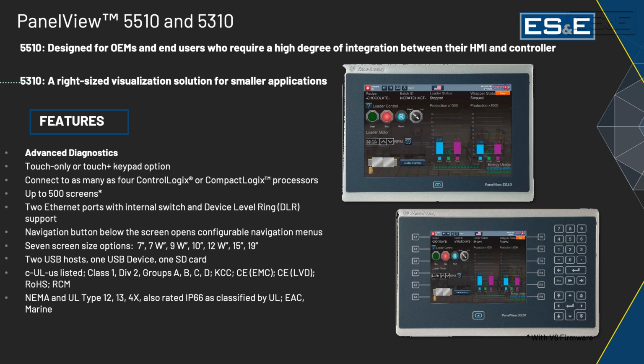So yeah, did you know it has advanced diagnostics? Did not know about the automatic diagnostics. The one cool thing about that is anything that's hooked up and connected to your control system, if something goes wrong with the device on it, power failure, cable unhooked or cut in half, you'll automatically get an alert sent to your PanelView saying what's wrong and what device it happened on. Yeah, but I got to program it, right? I mean, we've had diagnostics for years, so yes. No program is required. Oh. It's automatically embedded. It happens for you, so you don't have to do anything else on your end.